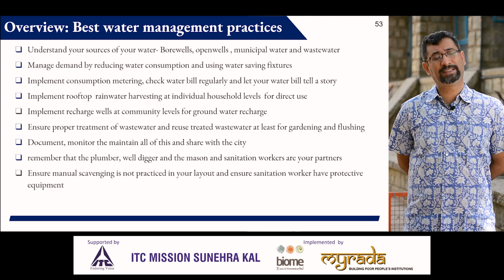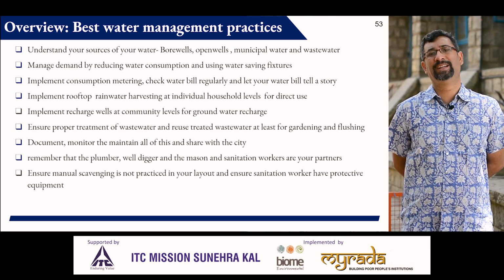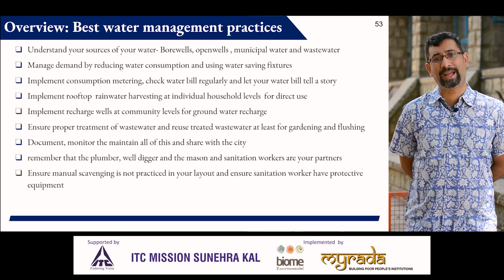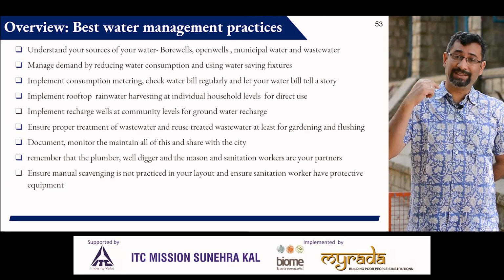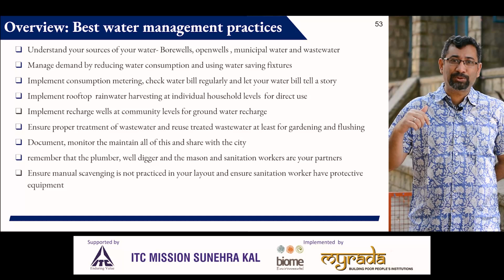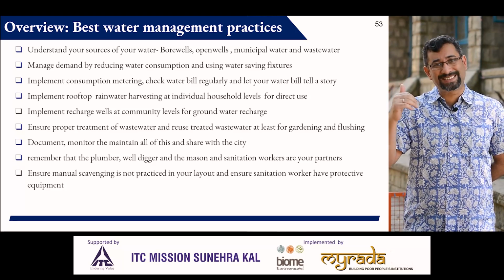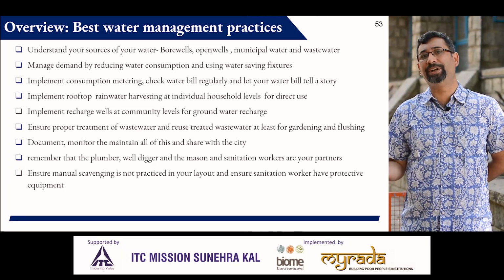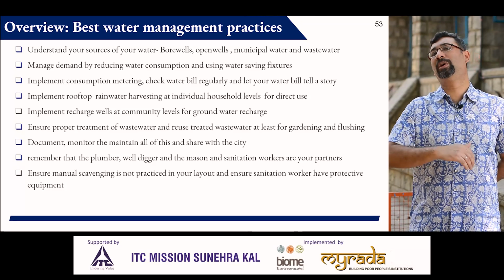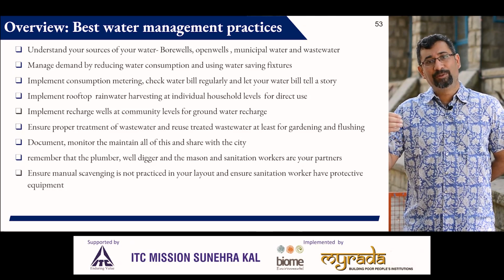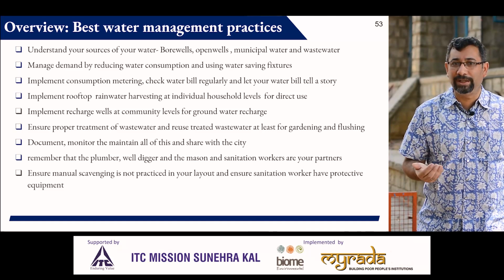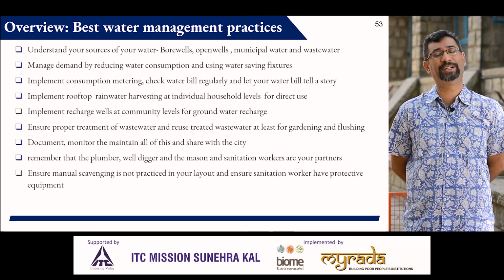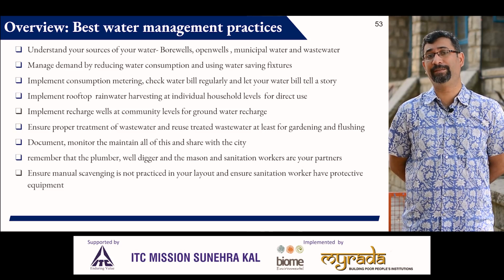So this issue of managing the demand is extremely critical, because if you manage your demand, if you reduce your demand as much as you can, then be it managing the supply of this water, be it managing the wastewater that you generate, becomes that much simpler. It becomes that much cheaper. It can make the difference in a community between investing in a 250 kiloliter per day wastewater treatment plant and a 150 kiloliter per day wastewater treatment plant. It means completely different economics, and therefore this issue of managing your demand should be considered very, very important.